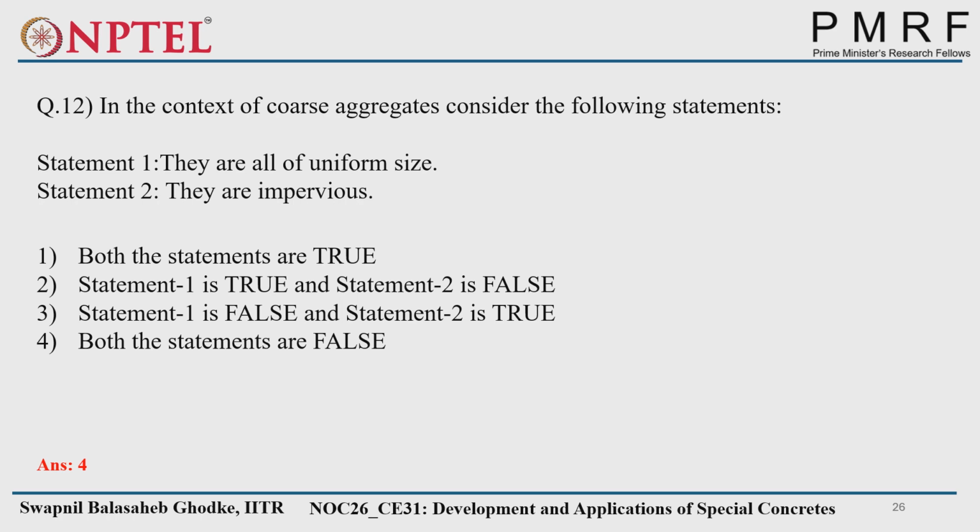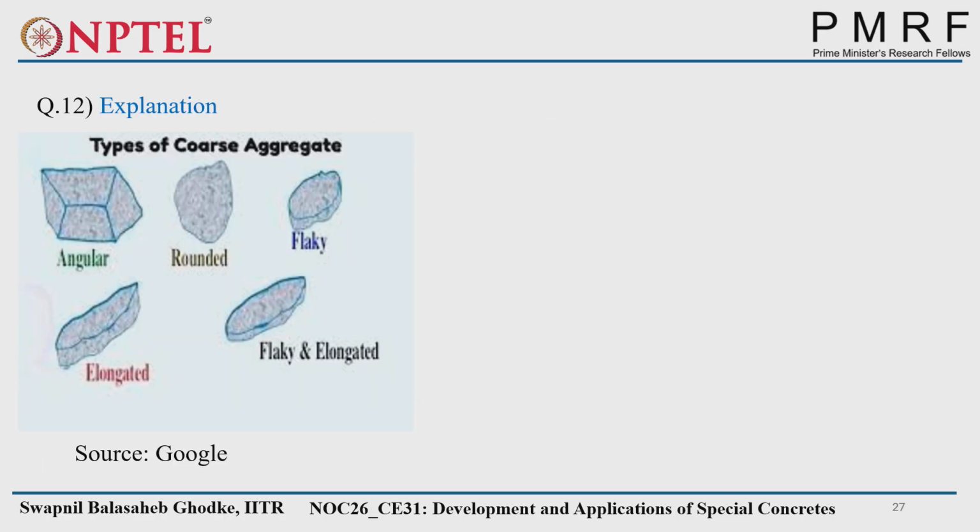We keep the coarse aggregate 24 hours in the water, then place it on a platform, not under the sun but on a normal platform, and remove the running water, and then only we use it. So that it will not absorb any water from the concrete. So it's not exactly impervious.